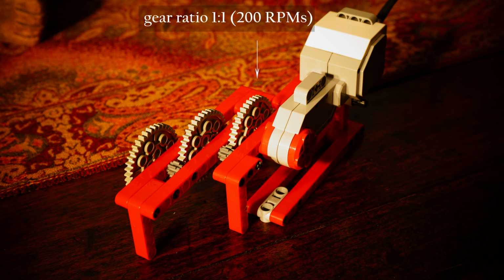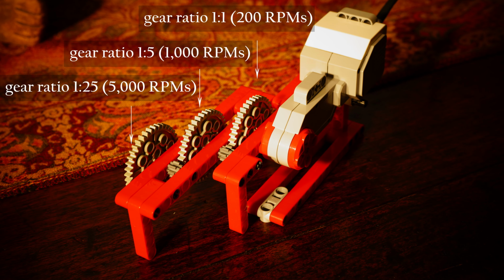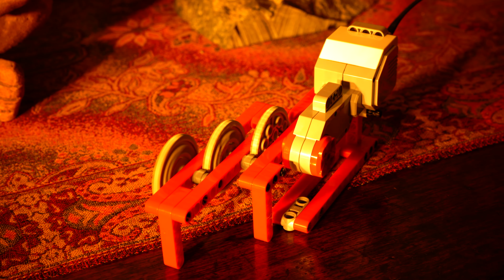Here, the first axle turns at 200 RPMs, the second axle, a compound gear, at 1000 RPMs, and the third axle, a second compound gear, at the required 5000 RPMs. This clip shows the progression from 1250 to 2500 to 3750 to 5000 RPMs.